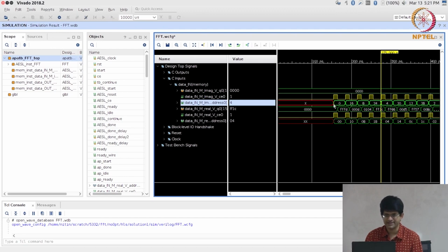That is the bit reversed addressing, because the first block itself is doing bit reversal. So effectively what is happening over here is the very first block is doing a bit reversed read, which means the way it gets implemented is the addresses going out for the very first set of reads are in bit reversed order. So it gets the data back in this format.